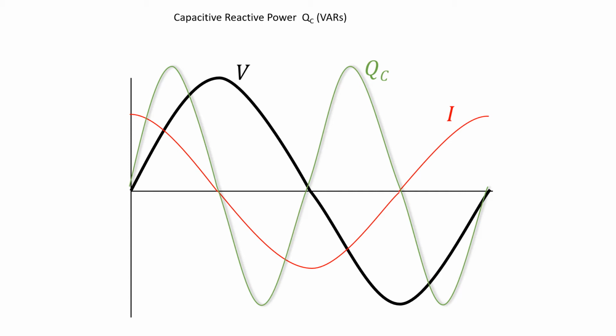And then that cycle would repeat itself, where during the third power pulse, our capacitor is charging up in the opposite direction. And then finally, during the fourth power pulse, our capacitor would be discharging or giving its energy back. Capacitors are constantly charging and discharging, where they're gaining power and then giving the power back. These power waveforms will become much more important once we look at both capacitance and inductance in the same circuit.